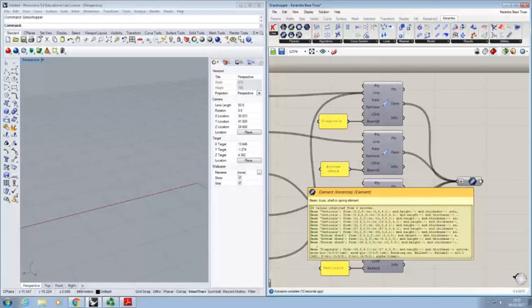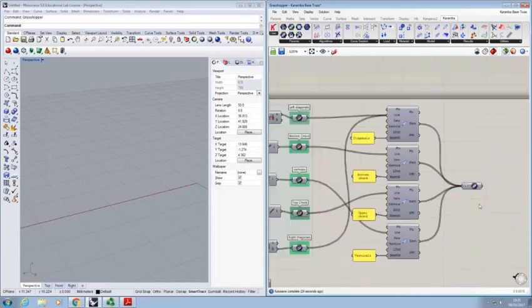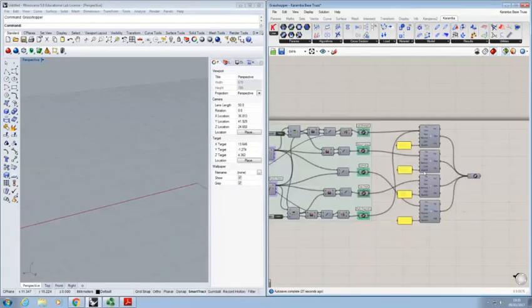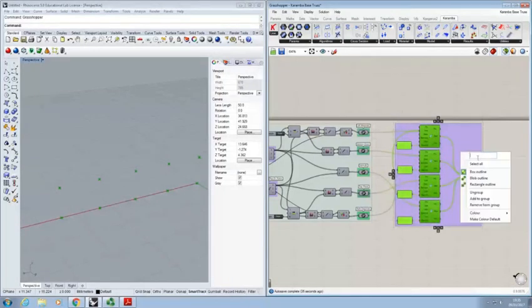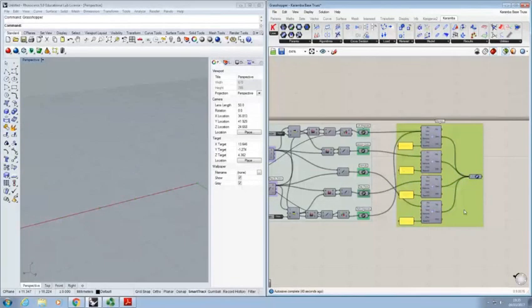So this is very interesting. You can see how the beams are defined. They all have a name, and they have a starting coordinate and an end coordinate. So this is the element setup complete, and we can create a group for that. We can call this group elements. Everyone good? Following?